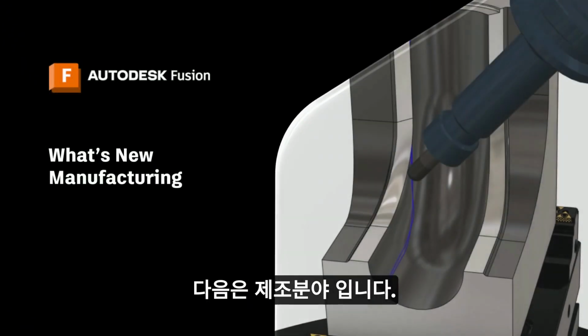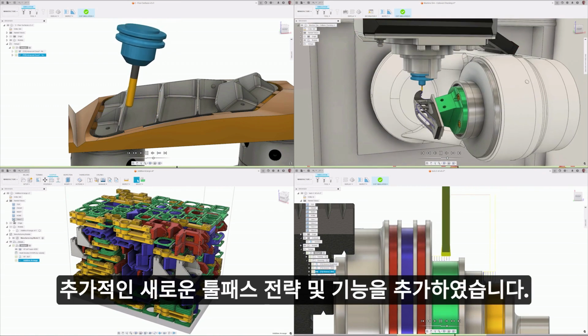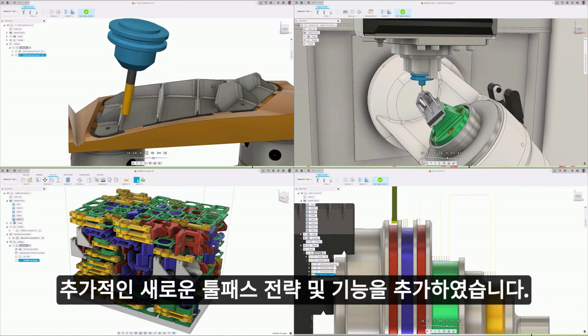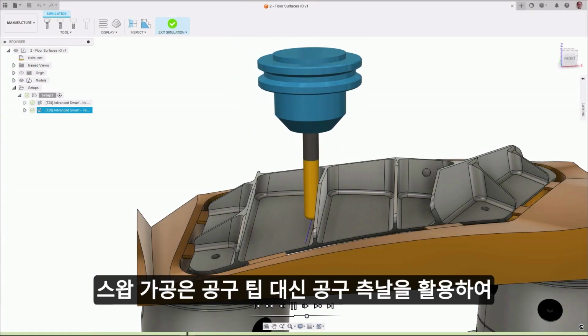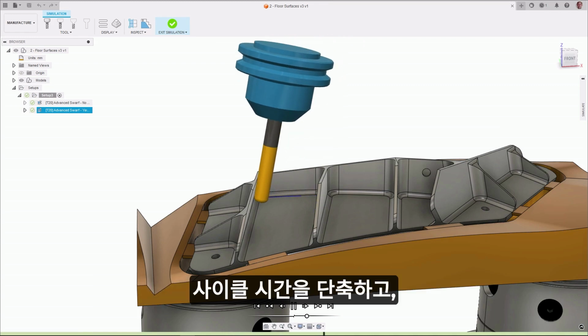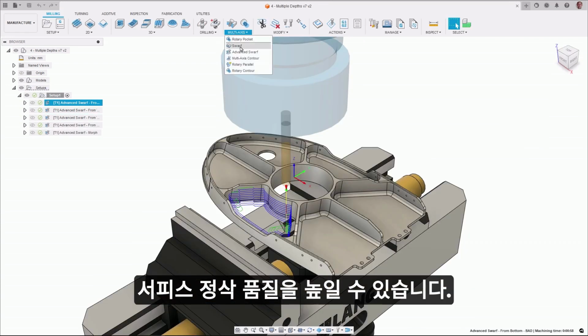Next up is manufacturing, and we are yet again adding additional new toolpath strategies and features to increase your machining, additive, and nesting productivity. Swarf machining utilizes the side of the tool instead of the tip, reducing cycle time and in many cases can increase the surface finish quality.